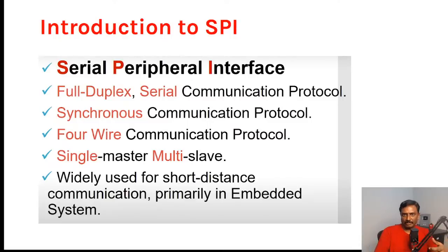Okay, so that is not recommended. If you want to connect more than two or three devices, then the best interface is SPI or I2C. But these are interfaces used only on the PCB level; they won't go to meter level, but they work on the PCB level.